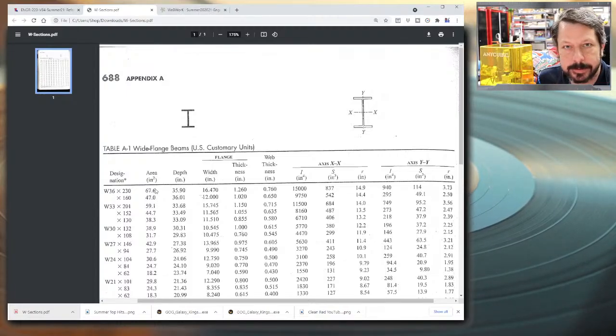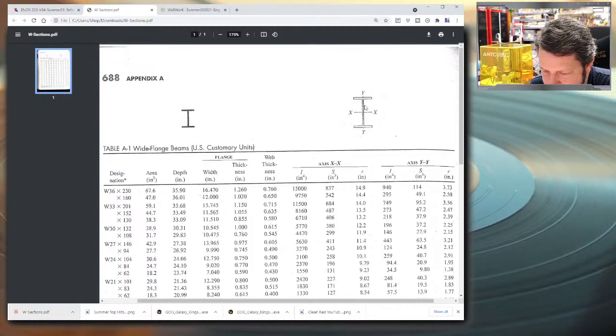Maybe you're calculating the stress that needs the cross-sectional area number. It's not really practical. They give you a kind of a view of the cross-section. You can see it shapes like an I-beam. It's not really practical to go in and try to calculate the cross-sectional area from dimensions. For one thing,